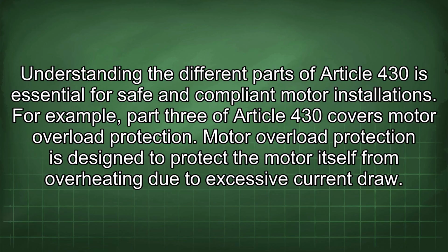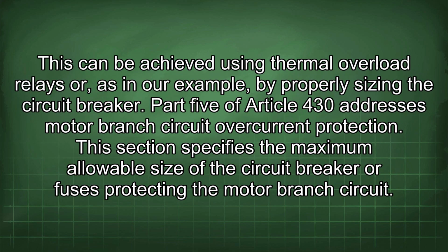For example, Part 3 of Article 430 covers motor overload protection. Motor overload protection is designed to protect the motor itself from overheating due to excessive current draw. This can be achieved using thermal overload relays or, as in our example, by properly sizing the circuit breaker.